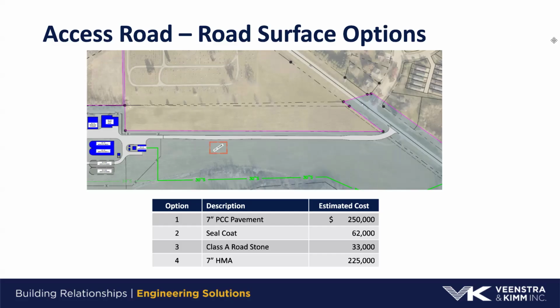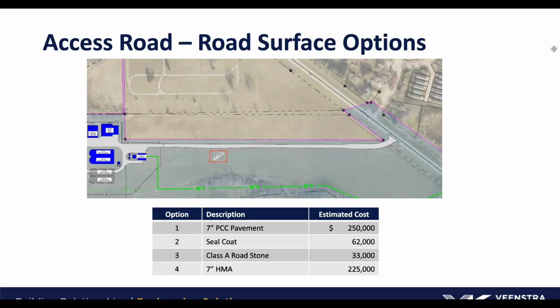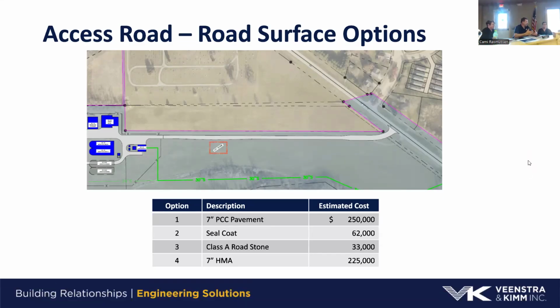Without knowing how that fits in with future driveways and everything else, potential buildings for the public works site, or if we do a site out here for Parks and Rec, we would probably be undoing a lot of what we do. So we really thought if we just did it as a smooth surface that they could just plow off to the edges and make sure we had drainage in certain spots, that was probably the least cost and best approach at this point. The curb and gutter doesn't really add anything in this situation.